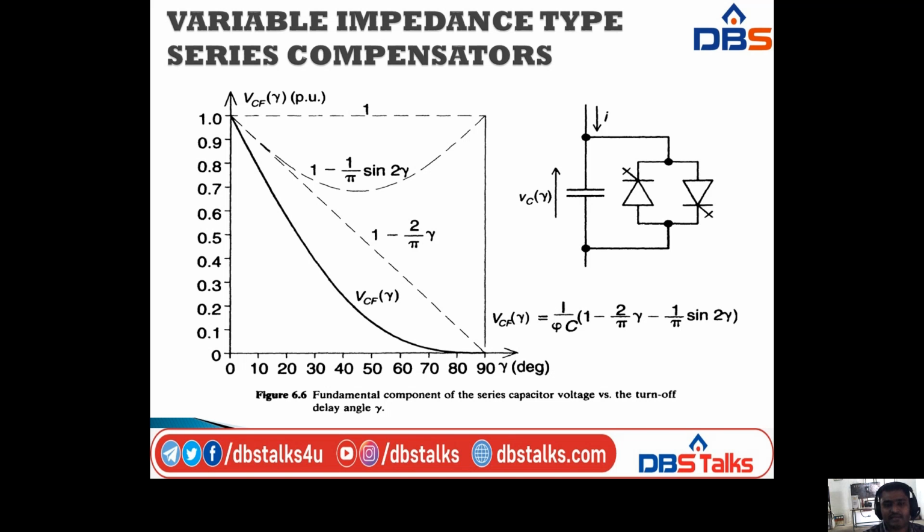The delay angle gamma is taken in degrees, from 0 to 90 degrees, and VCF of gamma, that is the fundamental voltage across the capacitor at delay angle gamma, is taken in per unit, that is 0 to 1 per unit. So we have the curves. We have three curves. One curve is VCF of gamma at 1 per unit to 90 degrees, and we have 1 minus 2 gamma by pi and 1 minus 1 by pi sine 2 gamma. Like that we have the curves.